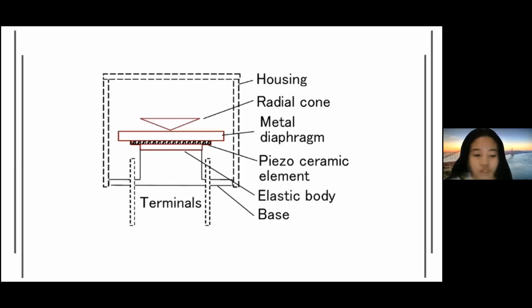So this is the ultrasonic transducer construction. The active element of the ultrasonic transducer is the piezoceramic element, which functions to convert electrical energy into mechanical energy in the form of ultrasonic sound waves. The backing is also added, which functions to control or dampen the ultrasonic frequency vibration from the piezoelectric active element, so it does not penetrate the back of the transducer, so that the ultrasonic energy radiates only forward.